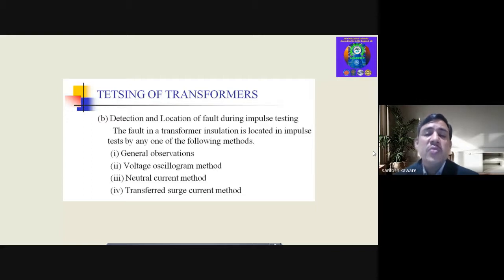I am remembering one thing, how manufacturing defects we especially experienced in HVDC. There was one defect, especially for the converter transformers. Whatever transformers we took into service, after certain days they were going to fail. They failed at the site itself during normal operation. That manufacturing defect was not with the design aspect, but especially with the selection of the oil, the coolant which they had used.